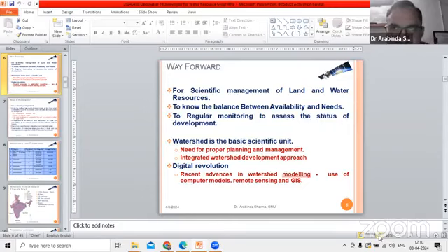So what will define that boundary? Mostly the mountainous region, the ridge of that mountain. In a topographic map, you will be able to identify that ridge line. That ridge line, which naturally exists on the earth's surface, will define the boundary, and whatever water falls within that region, rainfall water and so on, after meeting all the requirements, all kinds of abstractions like absorption, interception, evapotranspiration and so on, the excess water will appear as runoff.